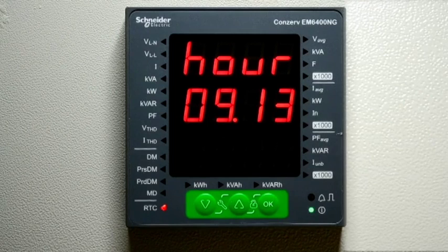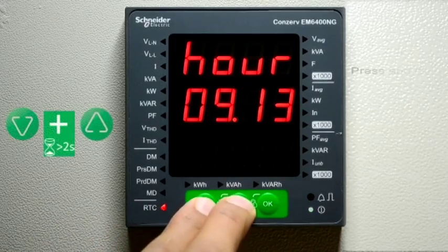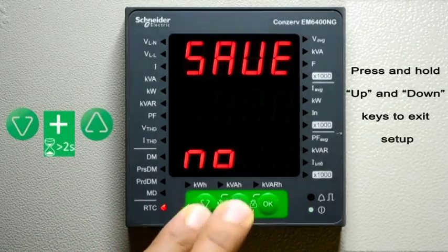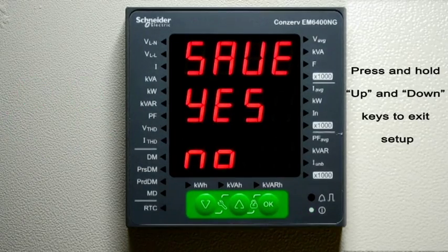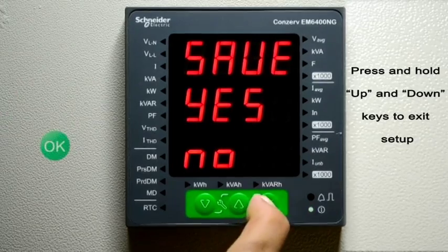Apart from this, the POP versions will have a set of settings related to pulse output configuration. These settings are similar to LED settings as described earlier. Once you are done with these settings, press the up and down keys simultaneously to exit setup. The meter will prompt to save changes. Select yes to confirm changes.